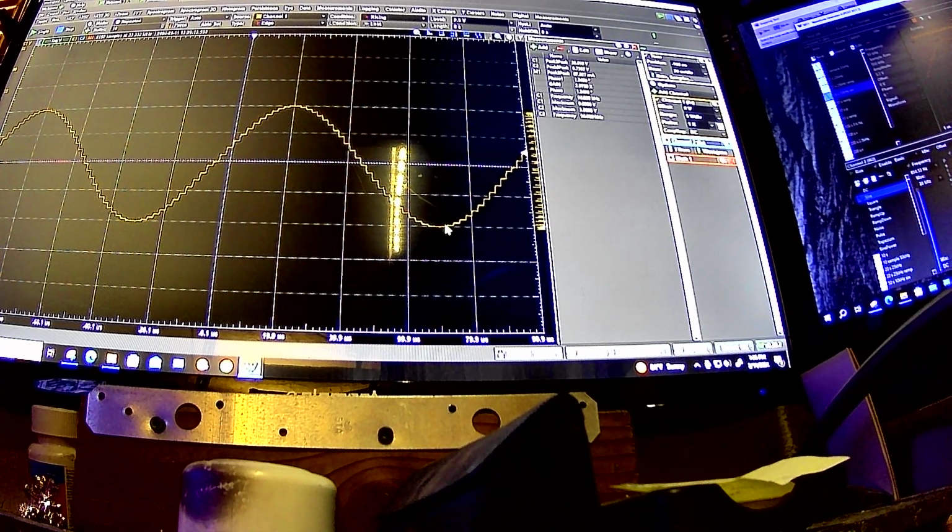And again, at 50 samples, we have 50 samples on the positive side, 50 samples on the negative side, so that's about 25 vertical and 25 horizontal, or 50 total peak to peak. So that's still pretty low, I mean, what is that, like a 6-bit DAC? So that's what a 6-bit output waveform might look like, although it wouldn't look quite this smooth, because this is higher than 6 bits.